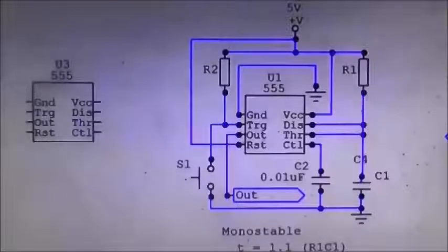They provide a network, and the network feeds a couple of comparators, and in turn the comparators feed a flip-flop, which feeds an output driver, and there's also a transistor in there for discharging capacitors. And what happens is that the voltage on the comparator is passed to the flip-flop, which is a set reset latch. And depending on what the set reset gets, it'll either put the output driver high or the output driver low.